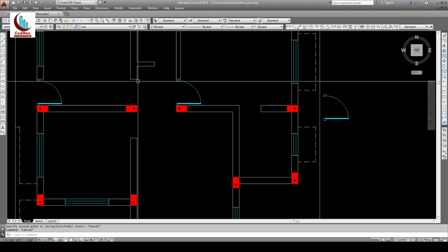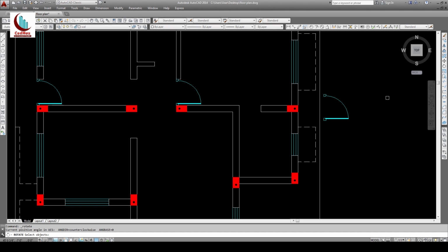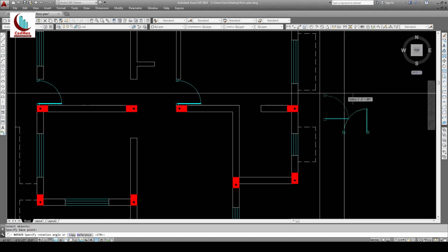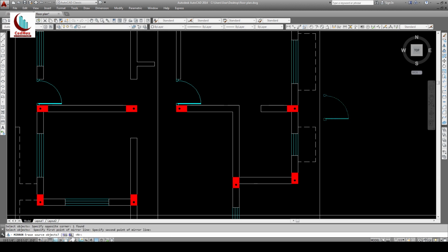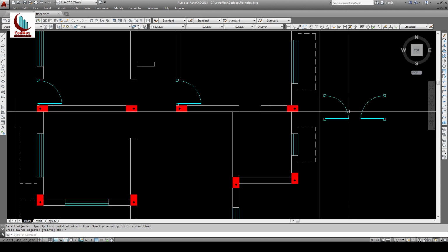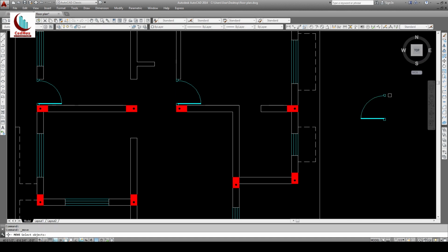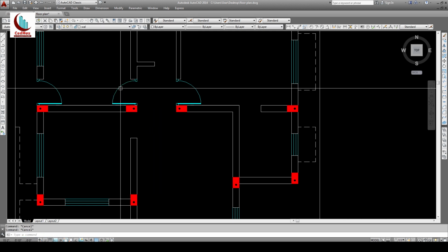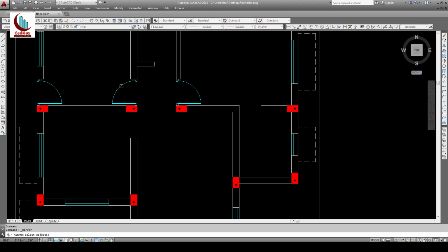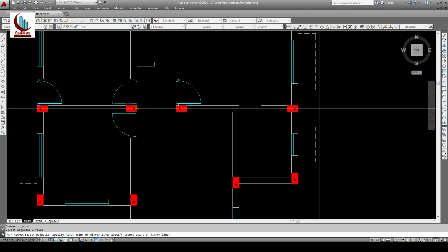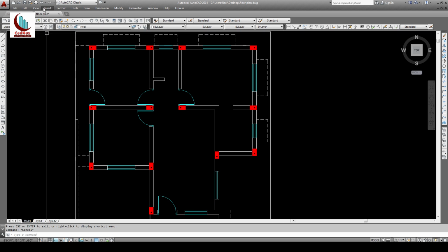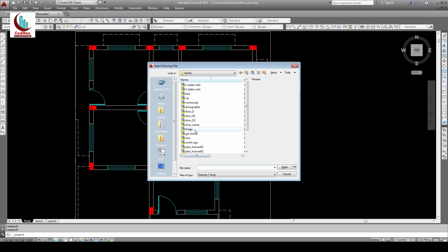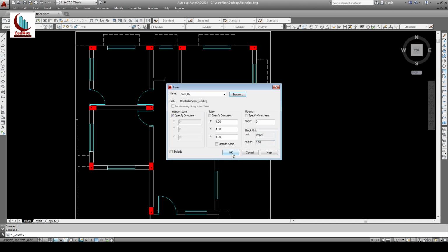One door here, here. Okay, next one is here, but the orientation we have to change. Rotate it like this, or you can use mirror. Like this, mirror like this. Do you want source object? No. Okay, move this point, second point. Okay, we want one more door here. You can use this, you can mirror this. Okay, select this as the first point and the second point. Okay, done, good. Okay, now next we have to place toilet doors, which is T2. Okay.